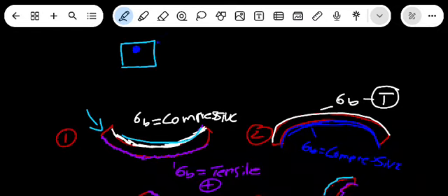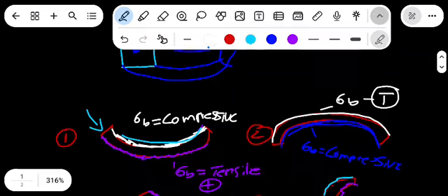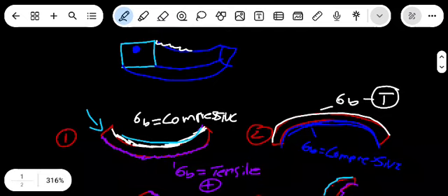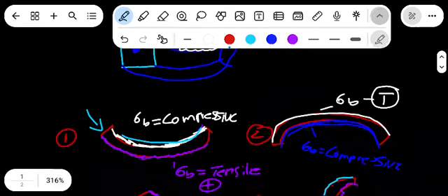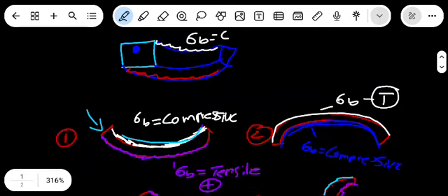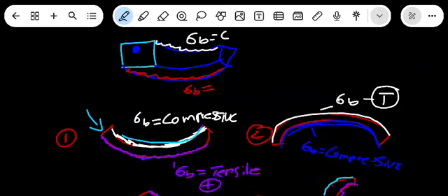While here we'll experience our bending like this, these portions will experience what? As you can see, this part is a bending stress, whereby we know that it is compressive. Then this side will cause a bending stress whereby it is tensile.